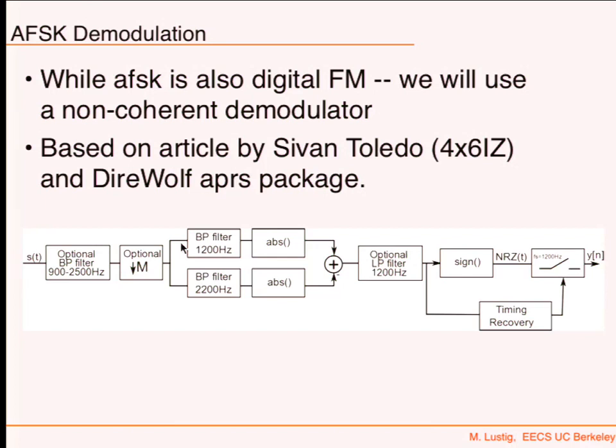And again, this is optional, but as it turns out, it does improve the detection. And what we're going to do is we're not going to do exactly 1200. We're going to give it a little bit more width, because really it's a balance between rejecting noise and keeping all your signal. So I think 1.2 times 1200.